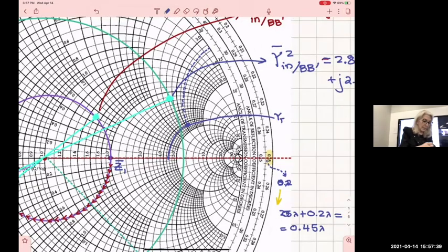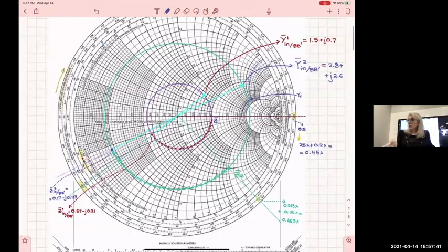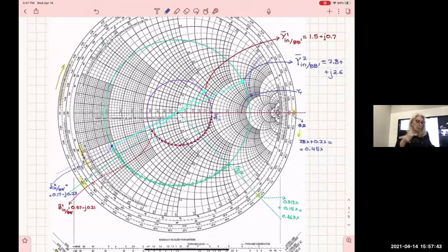So practically, now that I have the total admittance, from the circle of the transmission line it goes both from the impedance and through the admittance, all right? For all impedances, if you draw the diagonal, the other point is always the admittance.